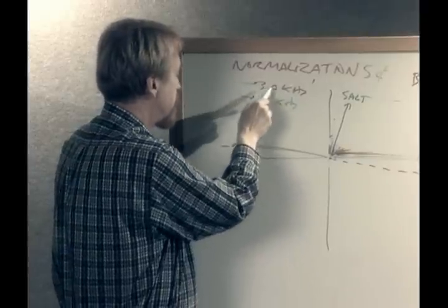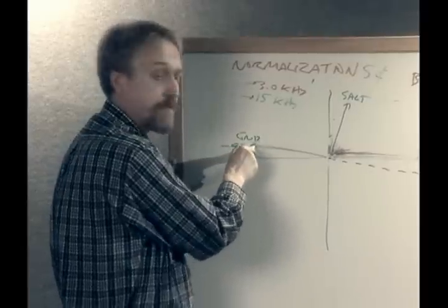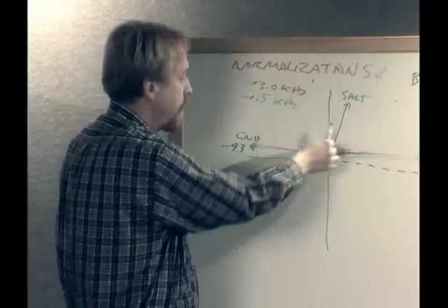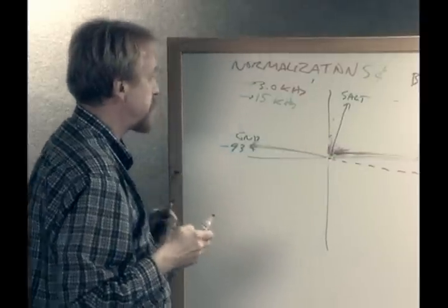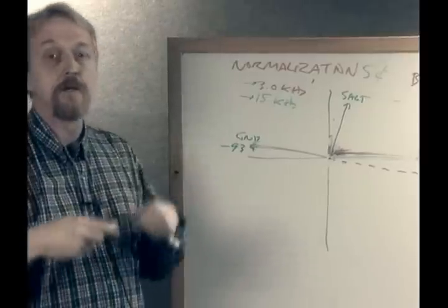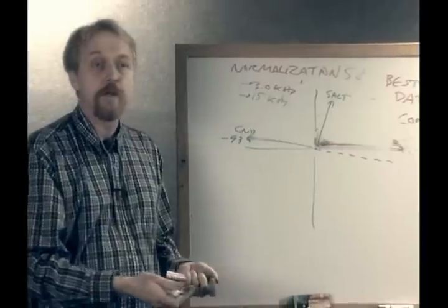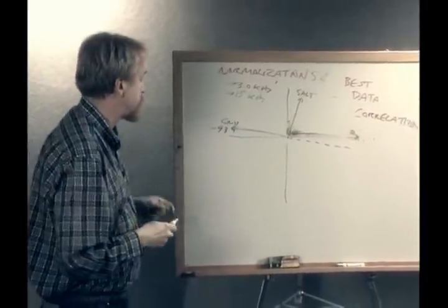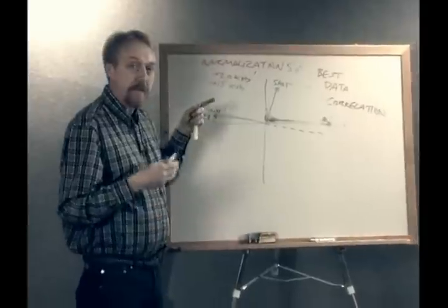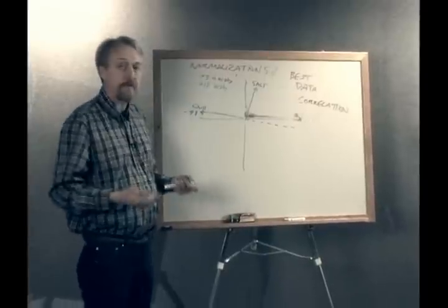But by doing an appropriate scaling and subtraction operation, we can get black sand or ferrous ground cancellation and saltwater cancellation simultaneously. So what you'll find is you take the DFX to the beach, balance to the dry black sand, begin to move down to the saltwater, and the detector will remain balanced all the way down the beach. And this is, of course, a very big advantage in all metal in terms of being able to pinpoint targets, measure their depth, and so forth.